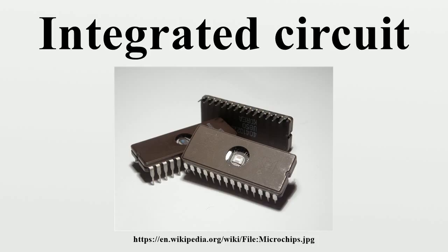In current research projects, integrated circuits are also developed for sensoric applications in medical implants or other bioelectronic devices. Special sealing techniques have to be applied in such biogenic environments to avoid corrosion or biodegradation of the exposed semiconductor materials. As one of the few materials well established in CMOS technology, titanium nitride turned out as exceptionally stable and well suited for electrode applications in medical implants.